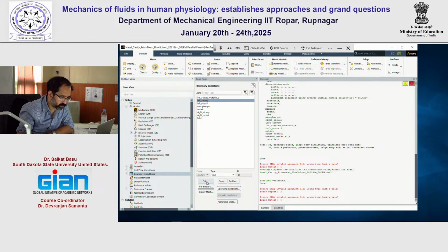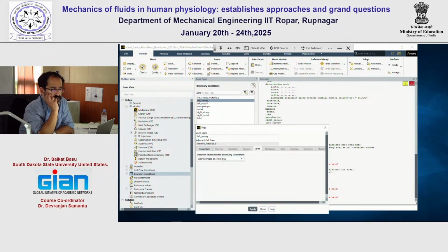And you probably would want to double check that the wall condition was done correctly, because I remember once there was a postdoc who was working for me. She kept on telling me that none of her simulations were ending. They were going on forever and ever. Can you guess what happened? She was keeping reflect boundary condition everywhere. The particles were getting reflected and reflected and reflected and never ending up anywhere. So that's a postdoc.